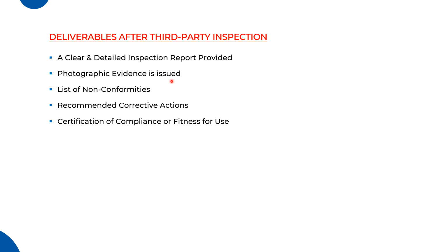There may be, in the height, in the mast at 80 feet, some corrosion or some cracks in the derrick. If there is an issue inside machinery, the photograph will make it easy to understand for the person who will see the report.